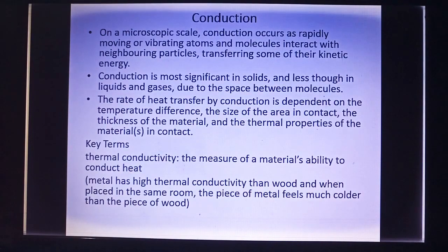Conduction on a microscopic scale occurs as rapidly moving or vibrating atoms and molecules interact with neighboring particles, transferring some of their kinetic energy. So in other words, heat is transferred through kinetic energy. Conduction is most significant in solids, unlike in liquids and gases.